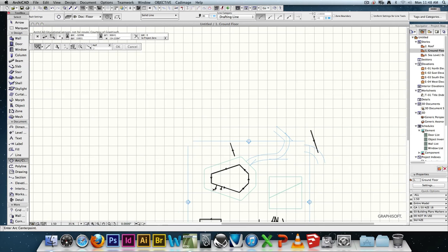So how should I do this? Let's use the old spline tool. I'm going to just use a natural curve. It's a nice big curve, and I'll curve it out a bit. Grab my polyline, offset. In fact, I'm going to show you the next tool, which is exactly the same thing, except it's multiple offsets, which is pretty cool.